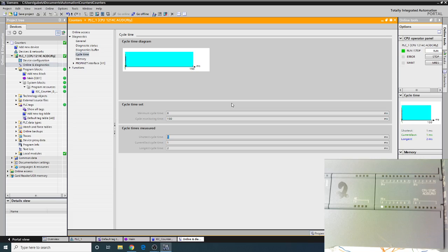Remember, we need a transition, and it needs to be able to grab that transition. So it needs to go from a high to a low. So if there's 1,000 bottles going past that sensor in a second, basically that sensor is staying lit as far as the program's controlled, right? Because it misses that drop because it's not updating that tag table fast enough. All right. We'd only get half. So we'd only get 500 per second. Now, that's still a lot of freaking bottles. 500 bottles going past something per second.